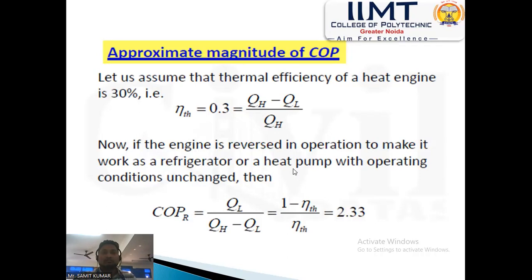The COP of the heat pump is inversely proportional to the efficiency of the heat engine, and the COP of the refrigerator is also related. The COP of the heat pump equals the COP of the refrigerator plus 1.